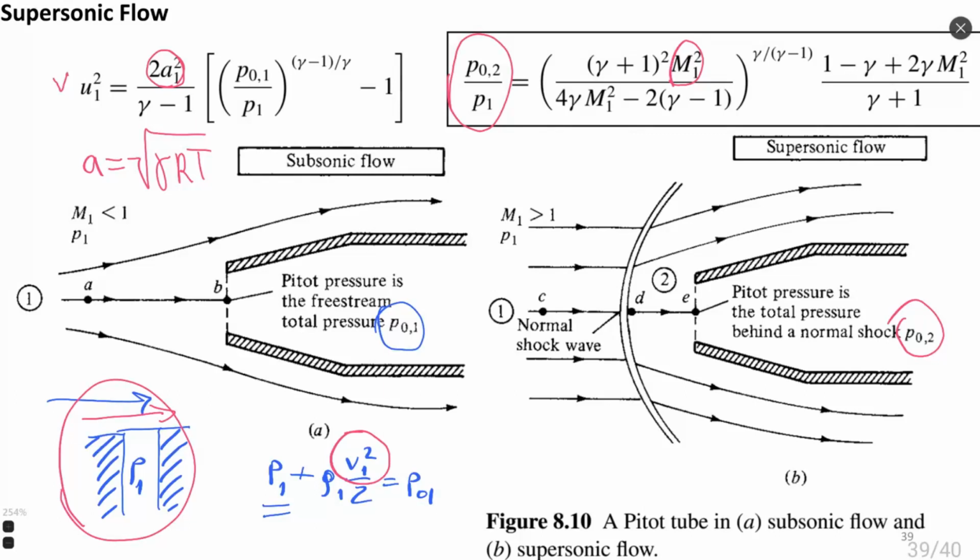result. What next? Once we receive the Mach number from this equation, we need to use some definition of temperature, either from onboard measurement, or from tables or a function of standard atmosphere, to estimate temperature, then estimate speed of sound.